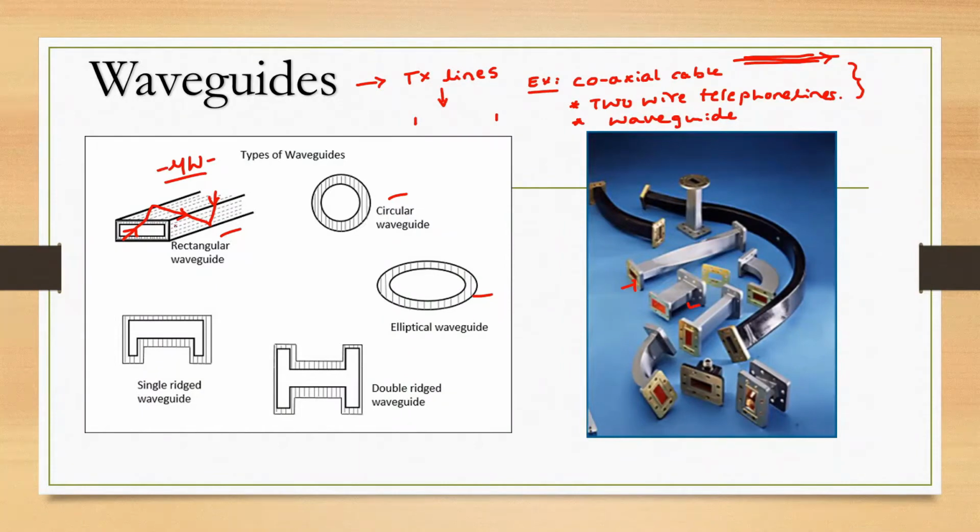So why have they been designed like this instead of using coaxial cable or any other center conductor? It is because the center conductors we use attenuate more energy. Since microwave signals have very little power, they easily get attenuated as the distance increases. That's why we need minimum attenuation from the conductor side. To achieve that, these kinds of waveguides have been designed.